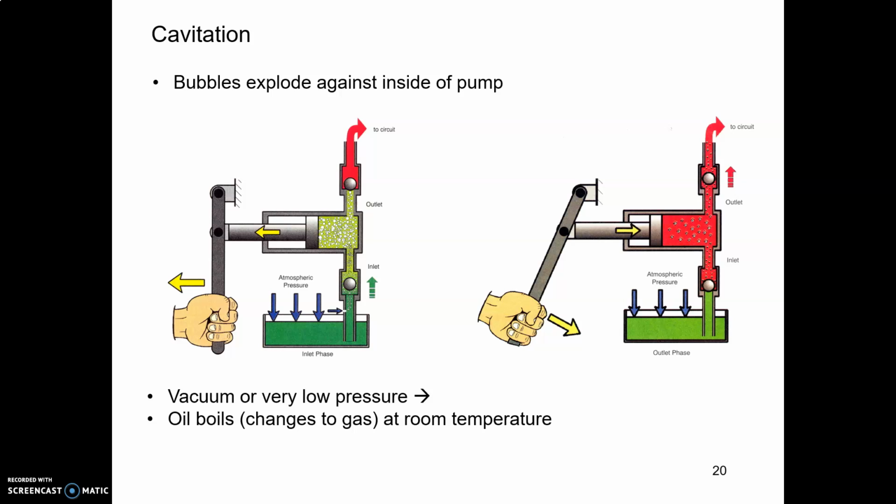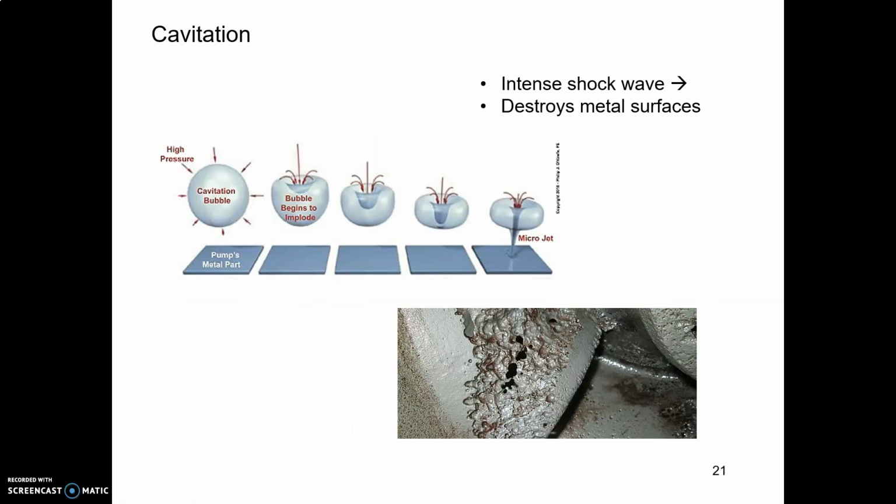Cavitation, and you'll know when your system is cavitating because it's loud. It sounds like the thing is beating itself apart, which it kind of is. Cavitation is where the oil actually changes from a liquid to a gas. It actually boils at room temperature, and that's caused by there being a vacuum in there, or at least a very low pressure, which might be caused by some kind of restriction or too small a thing.